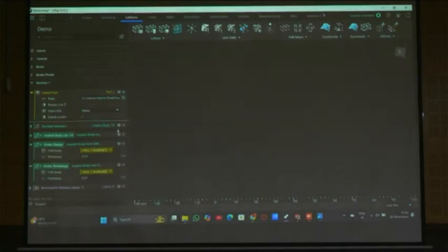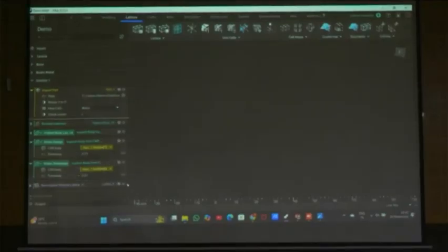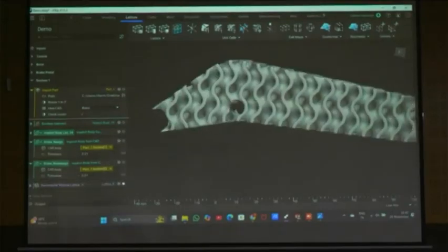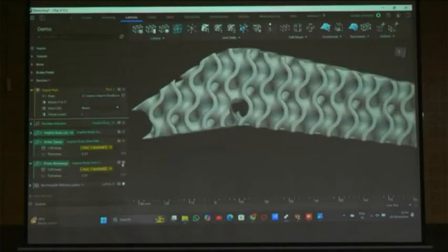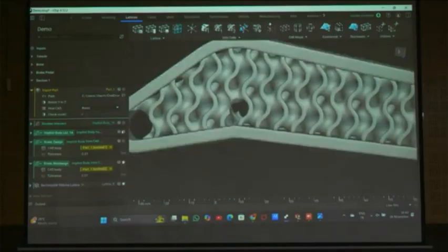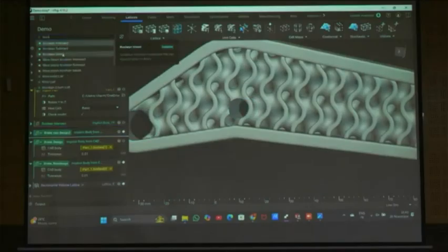We can combine these bodies. Which are the bodies? This one. Why are we applying this one? We are getting the non-design and this one. So we can break underscore non-design 2. Okay. So we can combine these three bodies now. Boolean union.